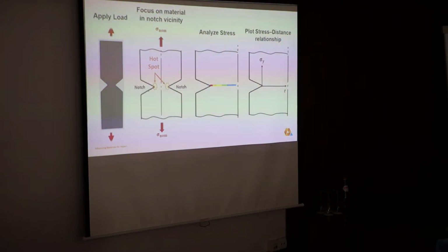By plotting this stress-distance relationship, we will get a curve that looks like so. Using this curve, along with a couple of critical parameters that are essential to performing TCD analysis and which may be calculated from a limited amount of experimentally generated fatigue data, we can make TCD-based fatigue predictions.